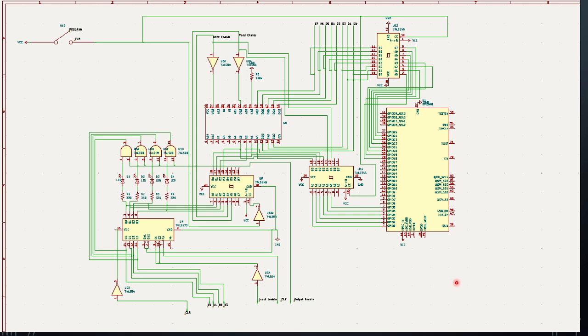And then we have the RAM module, which is one of the most complex parts of the computer. We have a 32K RAM chip right here, and the reason we use 32K is because there's no module on the market that has 16 by 8 words. You can see here we have the memory address register right here, and it constantly outputs its contents. And then you have the microcontroller, which is the interface between modern computers and the 8-bit computer, and it will write to the RAM module.